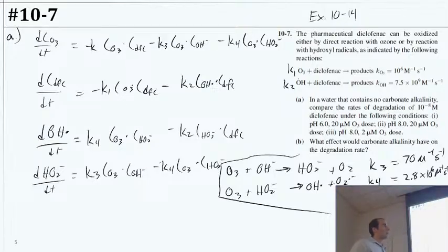One thing we might notice, it looks like our hydroxyl radicals react a lot faster than the ozone. That's a 10 to the 9th compared to 10 to the 6th reaction rate constant. However, if we stop and put in the numbers, we'll notice that we don't end up getting much of any hydroxyl radicals. So the rate at which this is reacting, especially compared to the case in 10.14, turns out it's going to be a lot faster with ozone and negligible with hydroxyl radicals.